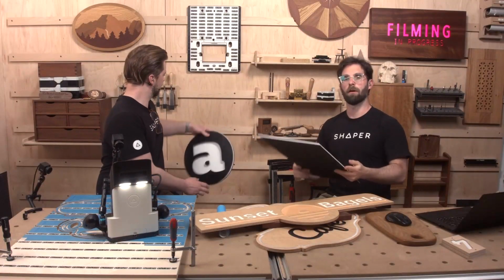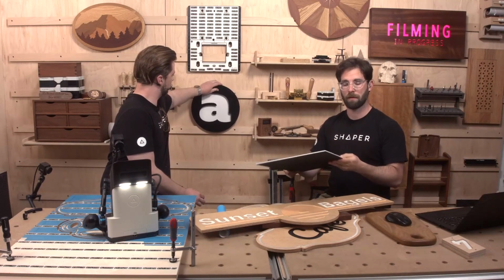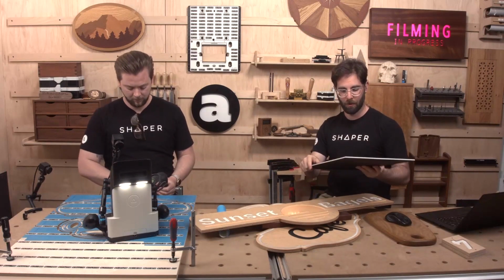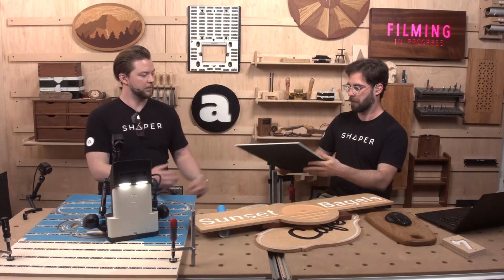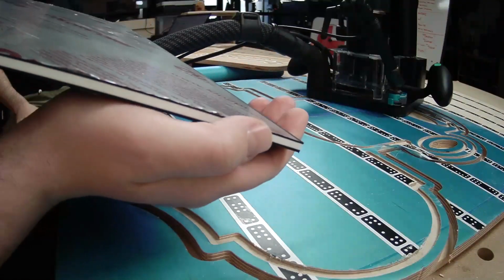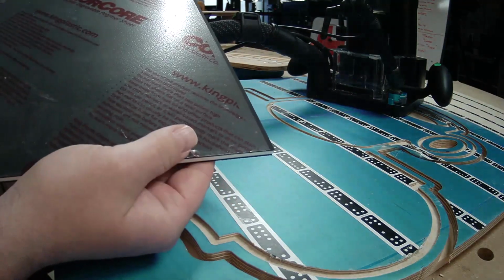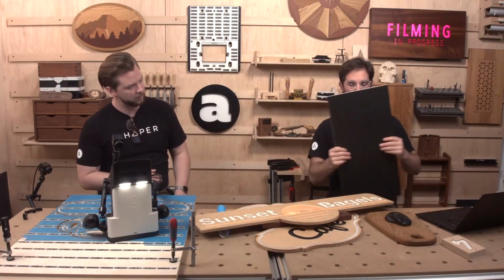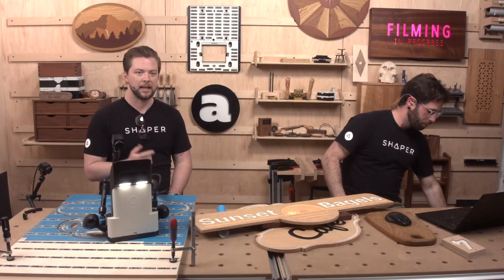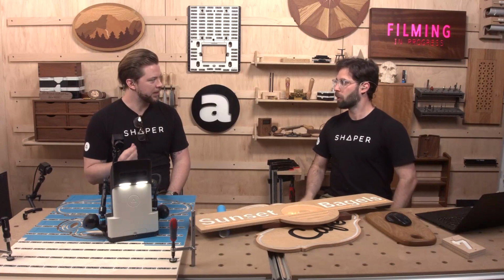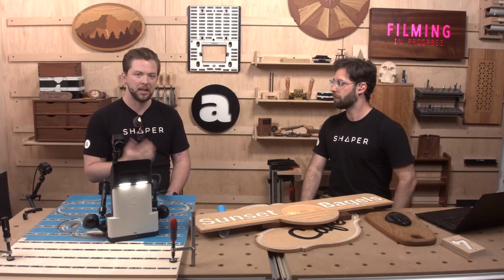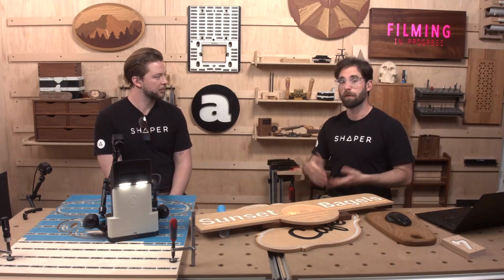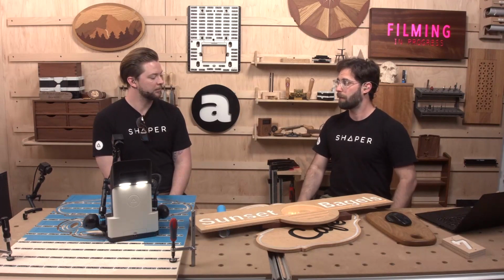All right, and one more bi-material kind of surface. This is HDPE, high density polyethylene. This stuff is called Color Core, and you could show it again on the bench cam. This is a layer of black on the outside, white on the inside, and then black on the other side again. And this comes in all sorts of colors. You can get it in red, blue, yellow, a bunch of different color combinations. Think like ADA signage, that kind of permanent caution signs. And when you cut through that black skin layer, you reveal the color underneath, and that gives you your graphic, which is pretty slick.